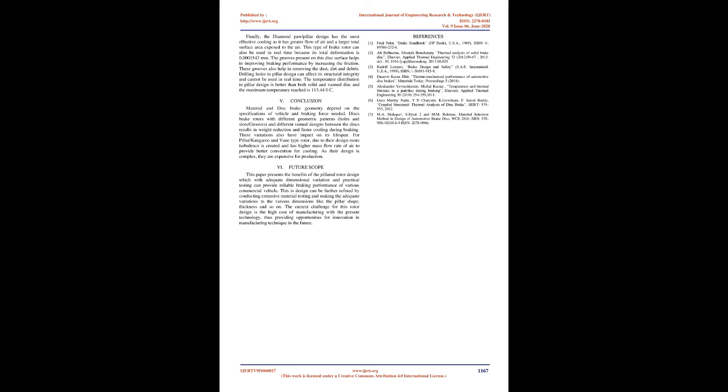The total deformation of the solid brake rotor is very low, at 0.0000698 mm. For a single stop, the maximum temperature of the solid type reached is 157.260 C.